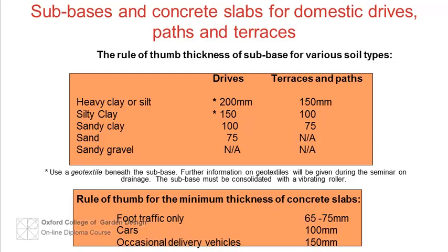The concrete slab should be cast in equal-sized bays, with provision for shrinkage joints round each bay and round any obstruction like drainage manholes. Bay size is to be about 4 meters in both directions. Previous screens show the appropriate mix. For example, PAV1 designated mix automatically includes an air entraining admix for the use on drives.